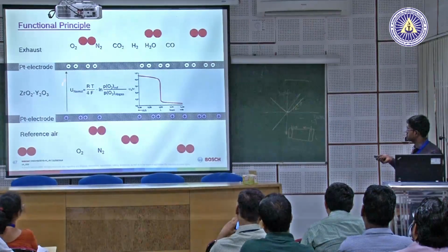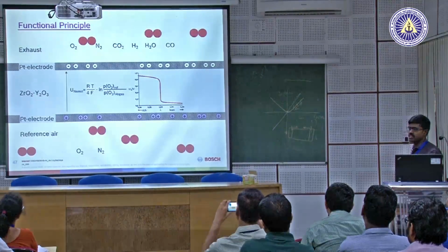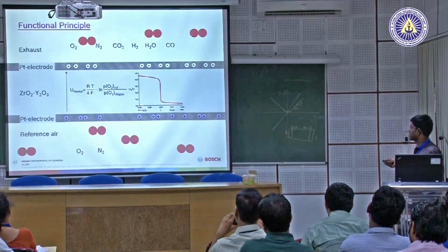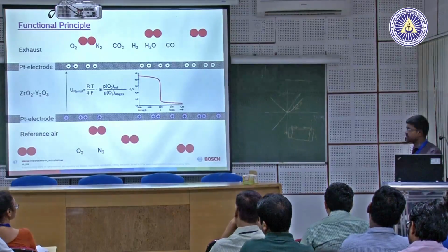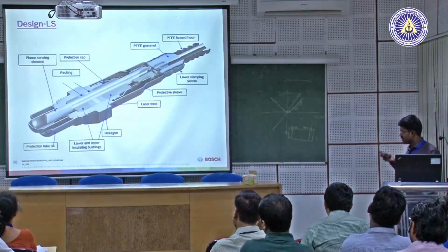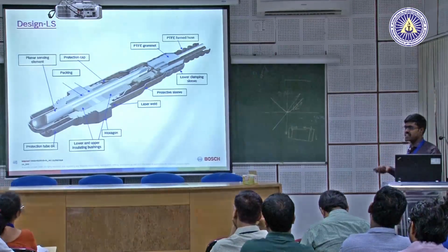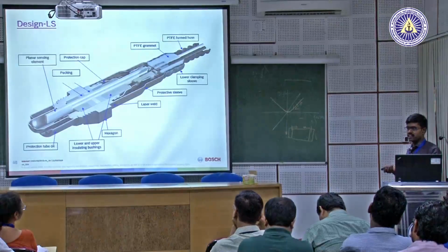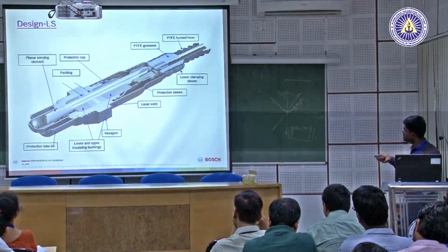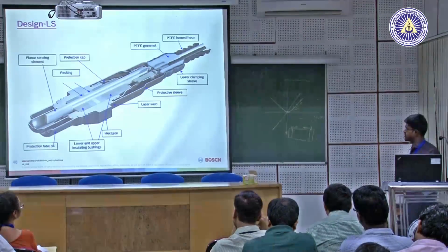So, that is how this is because of the partial pressure. This is how the Nernst voltage is calculated, and this is the typical curve of how it looks. The oxygen sensor, nitrogen oxide sensor, and particulate matter sensor are similar in design wise; only the sensing element will change. So, the design is carried over for all the other sensors also.